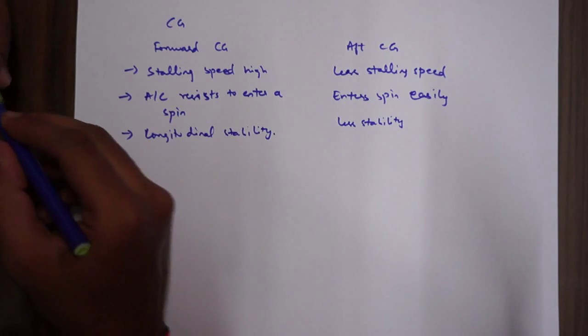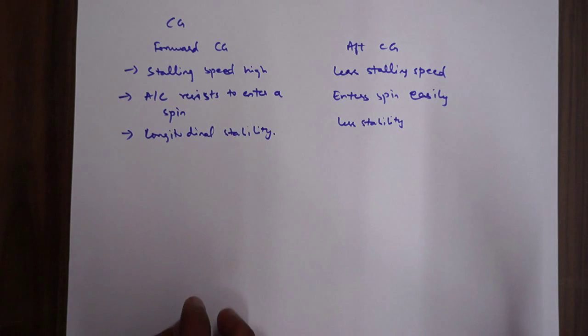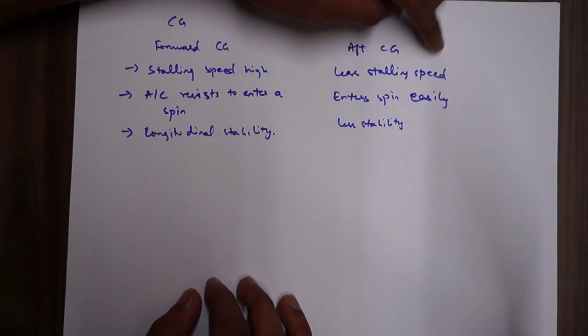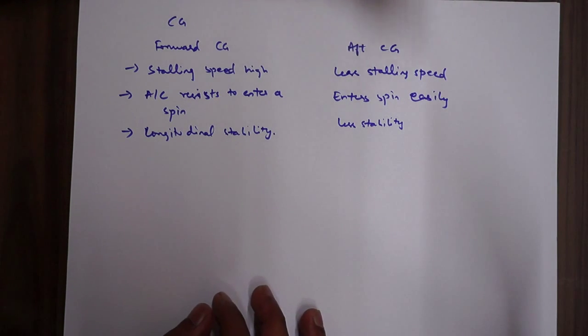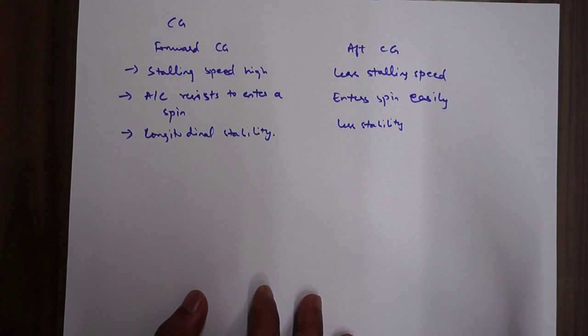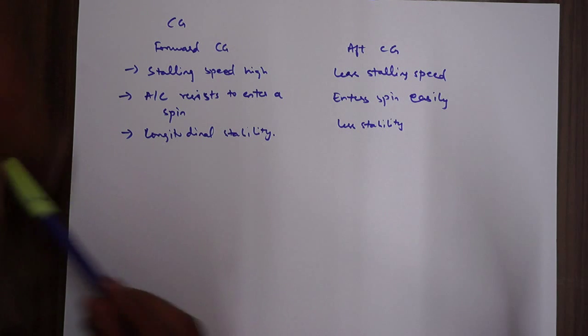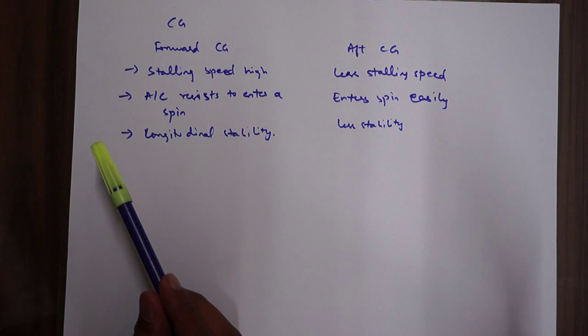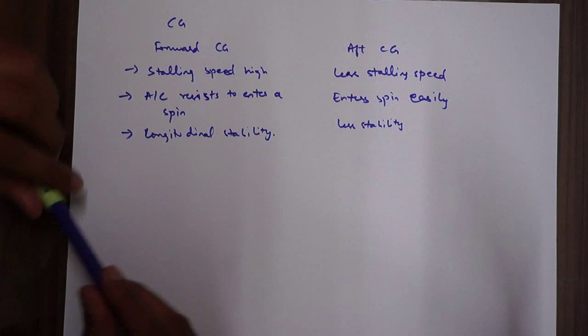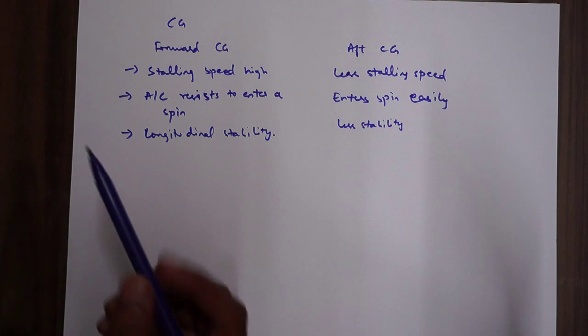Alright. So, if you exceed the aft limit, suppose the aft limit is exceeded, so the stall conditions are very drastically worsened and the stall recovery procedure becomes really tough. Okay, now we'll discuss different types of stall.